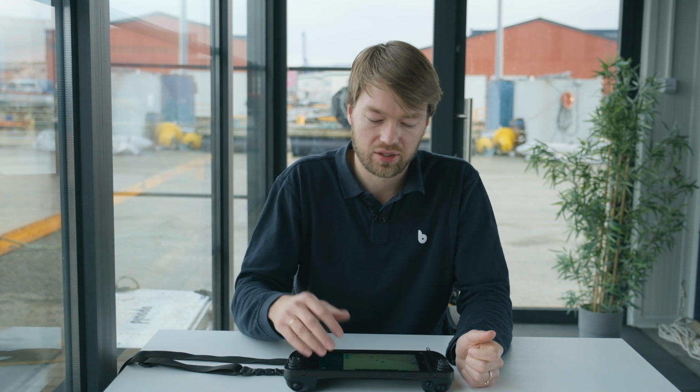So now I've shown you the required steps to get the best possible position with the DVL A50. However, if you do need a good position for longer operations, we recommend that you connect an external positioning system. This could be an USBL system or an UGPS system. Both of these will then be integrated in the app the same way and appear here under navigation sensors. You can also use a DVL together with the USBL. Then the two sensors will be fused together to give you the best possible position estimate.